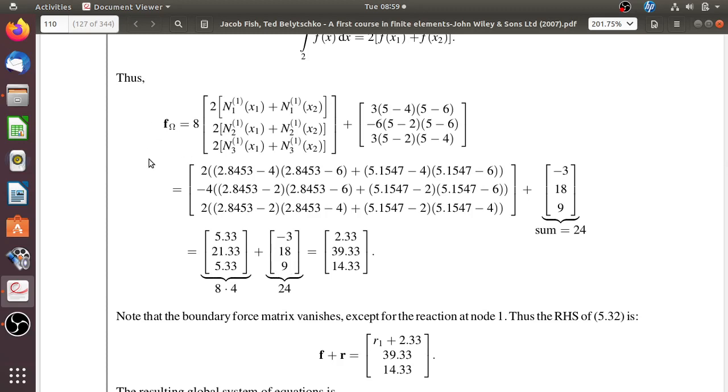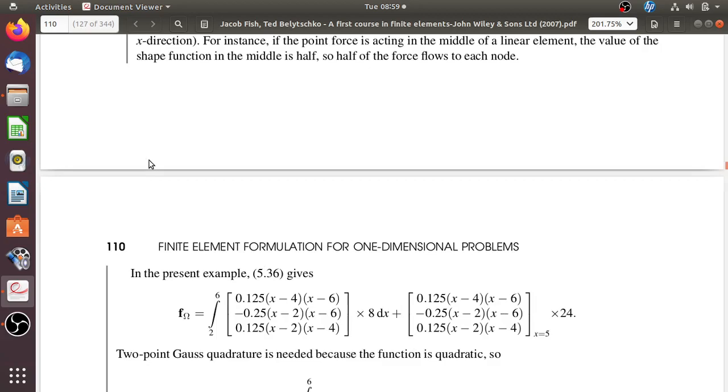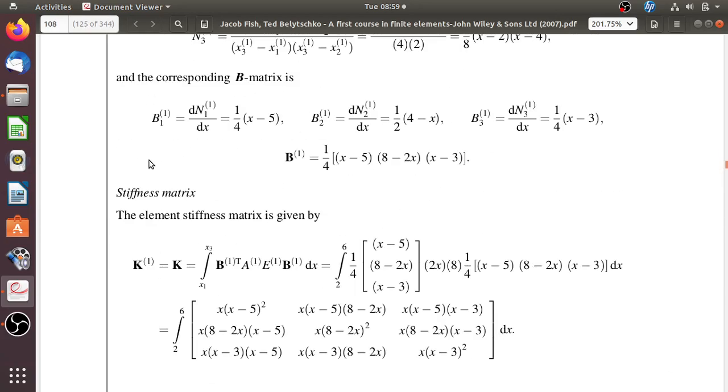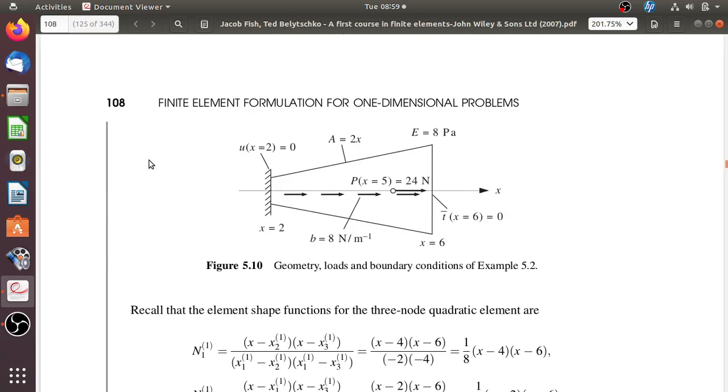Now there is something called a surface force, right? The surface force I will account only at the place where the Neumann boundary condition is given. So I can assume the surface force at this point is 0, the surface force at the center node is 0, and the surface force at this node is t bar, which turns out to be, for this case, also 0.